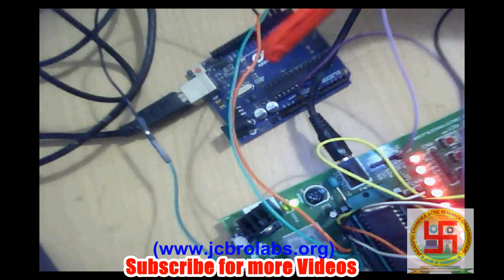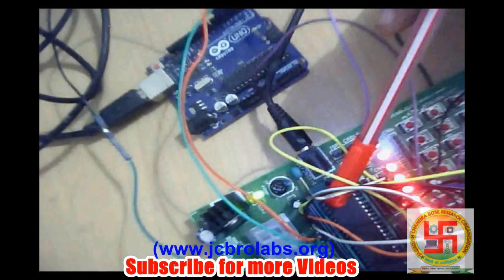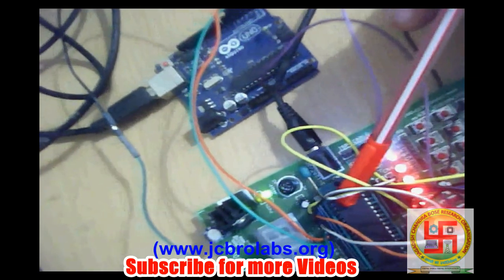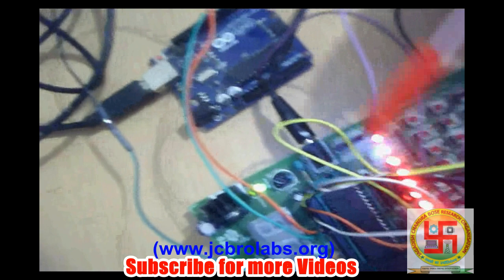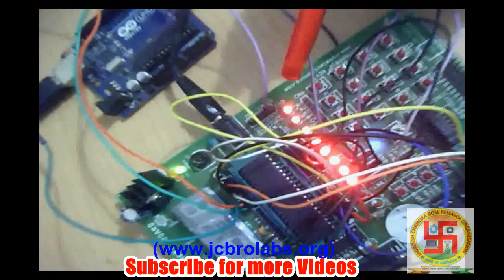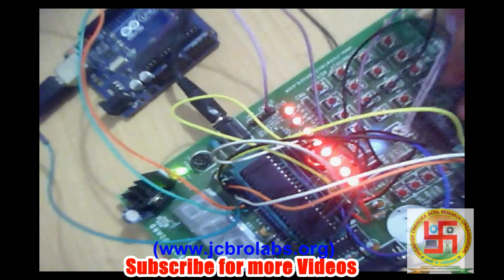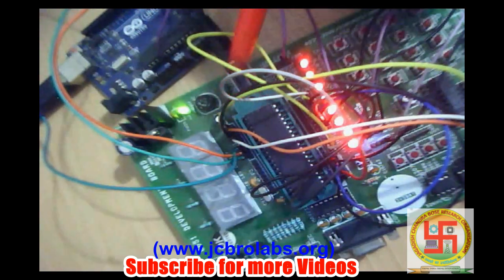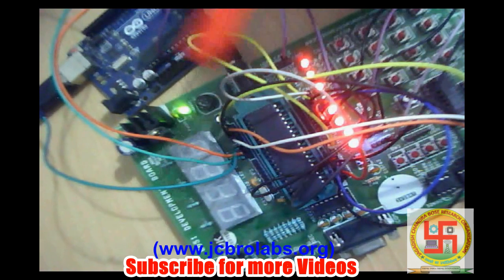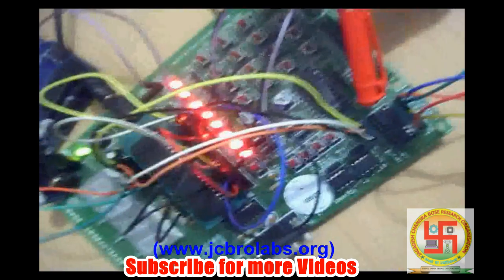So this is our programmer, the Arduino, which is used to program this 89S52 microcontroller. So we have burned the program into this IC, and here we have LEDs. These LEDs are running very fast, so the camera can't capture the blinking. Now, as we have seen in programming, 4 pins of port 1 are used to provide the sequence to the stepper motor.